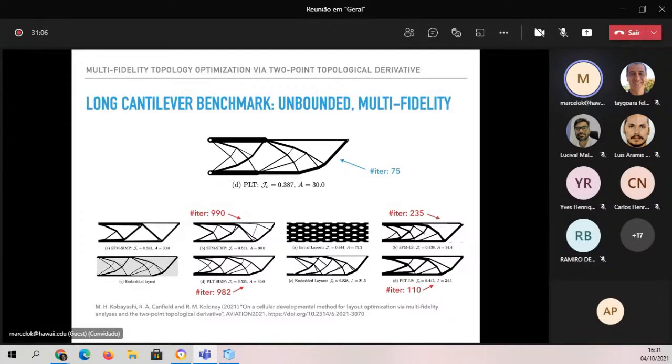Beams have information about the shape and thickness of the bars, but they have that as attributes of those edges in the graph, rather than a geometrical thickness in the domain. That's important because this allows us to use a beam model that is just one-dimensional, and is orders of magnitude cheaper than a two-dimensional plane strain finite element model.